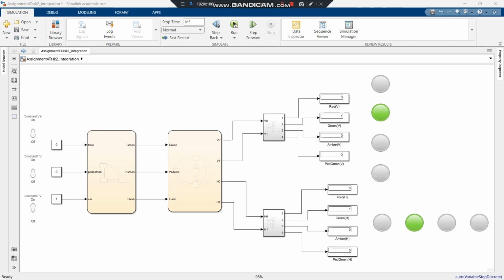So this train button will perform an action, which is flash action, which will toggle the red and amber lights with a frequency of 10 Hz. And so the next one is the pedestrian button, which has the second high priority.